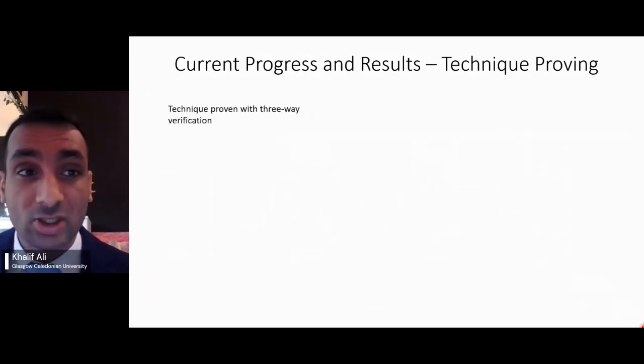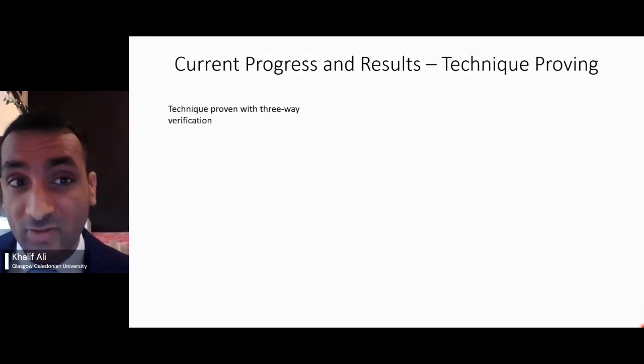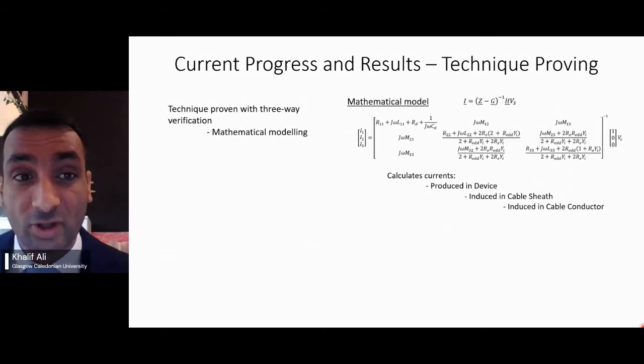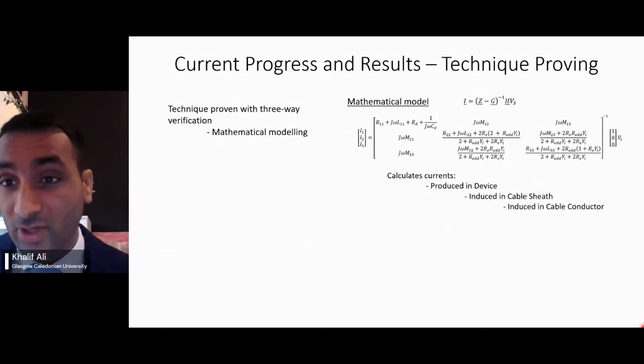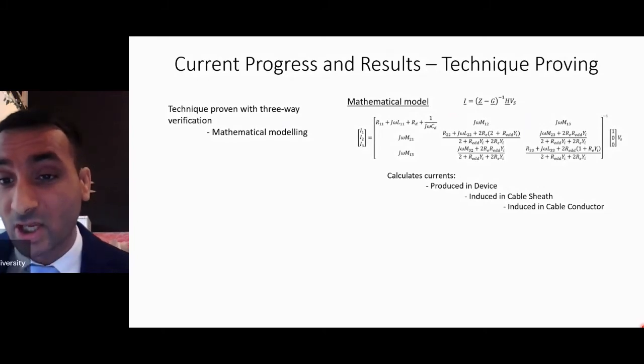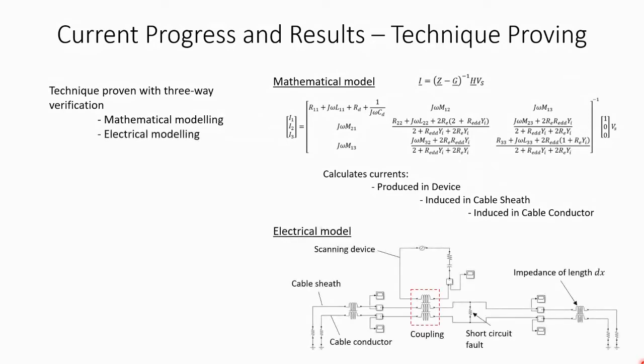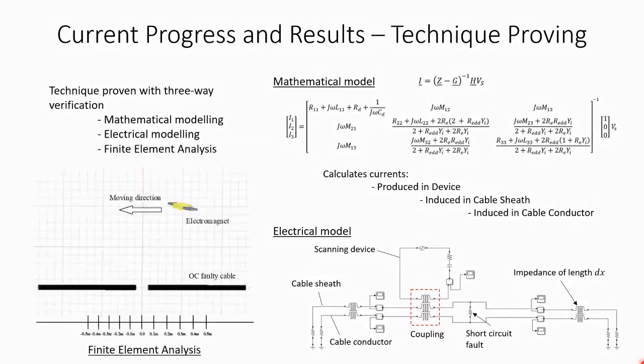The technique of our concept has been proven in 3-way verification. That is, we have created mathematical models. The matrix shown in my presentation calculates the currents produced in the device, induced in the cable sheath, and induced in the cable conductor. We've created electrical models on MATLAB Simulink. We also created finite element analysis models on ANSYS Maxwell. And the results produced by these 3 models are very closely matching and therefore verifying the technique.